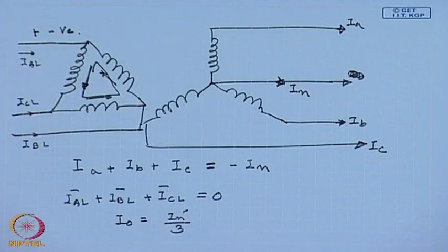This is necessary to prevent distortion of the secondary side voltage. So, if you have a star connected winding supplying unbalanced load through a neutral connection, then the other winding should preferably be delta connected.